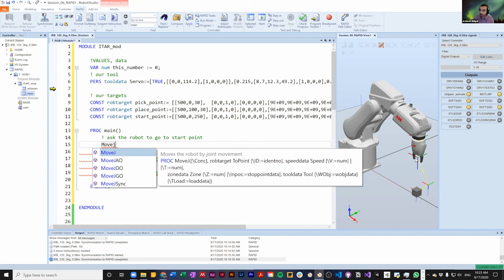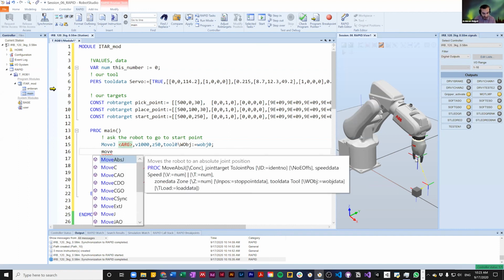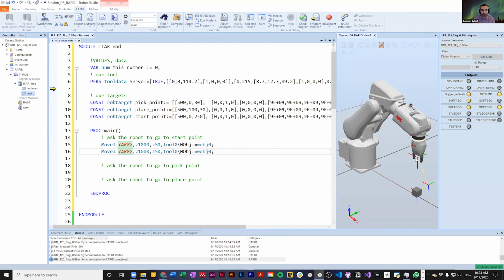If you want to get even more comfortable with this whole workflow, if you double tap the Tab key on your keyboard, so I'm going to hit Tab twice, it actually populates the whole command for you. You just need to place some extra data in it. So I just typed MoveJ and then double hit Tab, and it makes this whole line for me.